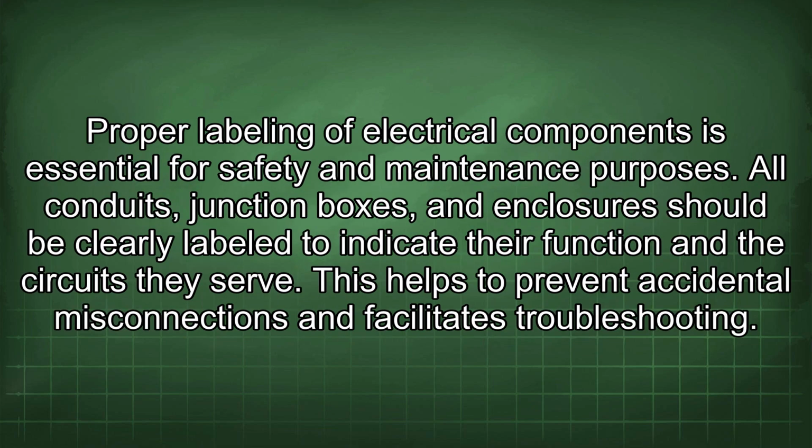Proper labeling of electrical components is essential for safety and maintenance purposes. All conduits, junction boxes, and enclosures should be clearly labeled to indicate their function and the circuits they serve.